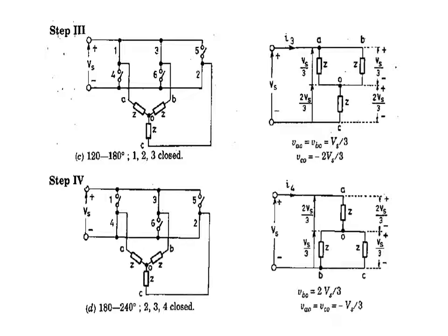All these circuits show equivalent circuits for conducting the upper and lower group of thyristors in a manner of 180-degree mode of operation.